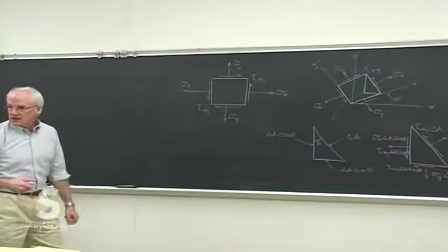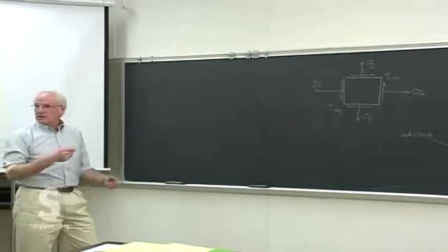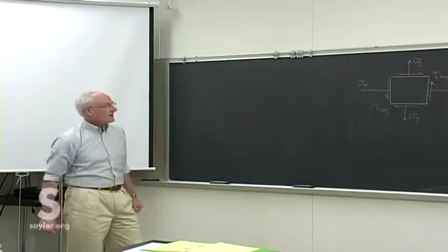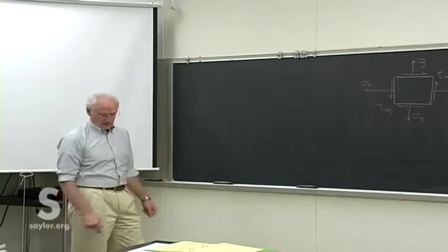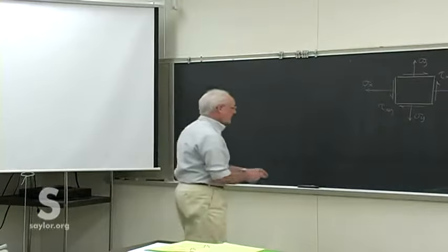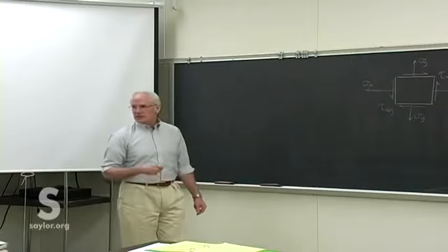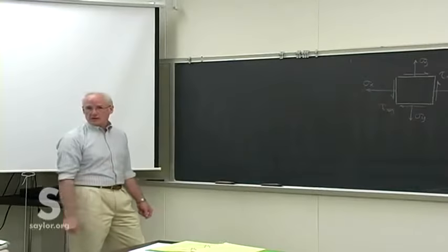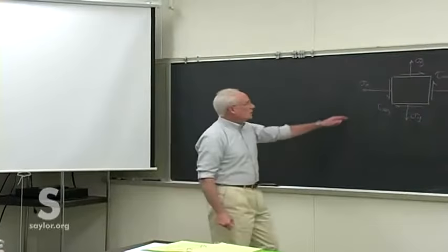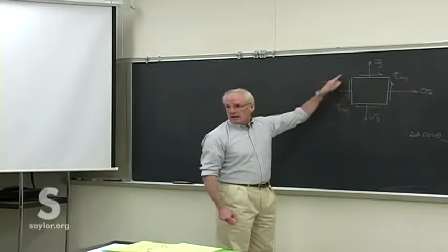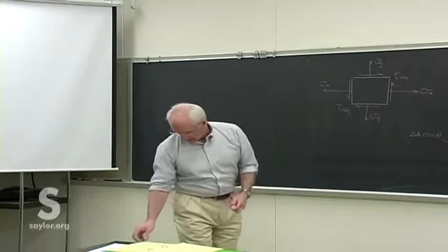And that way we can see whether the stresses of greater concern are at some other angle than just the original horizontal and vertical. Remember, for pure axial loading, we found the shear stress was at a maximum at 45 degrees, something we would not have seen if we had just stayed at the original horizontal and vertical angle.